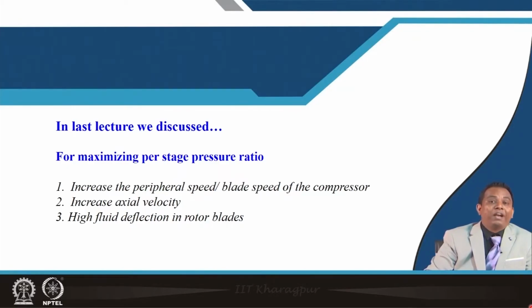Using a higher blade angle or higher blade deflection angle will lead to flow separation. Since we are working under an adverse pressure gradient, separation of flow will happen on the suction surface of the blade, or maybe on the pressure surface of the blade.